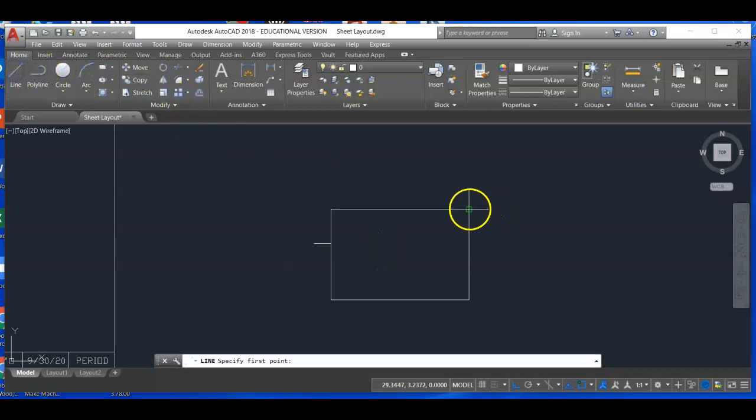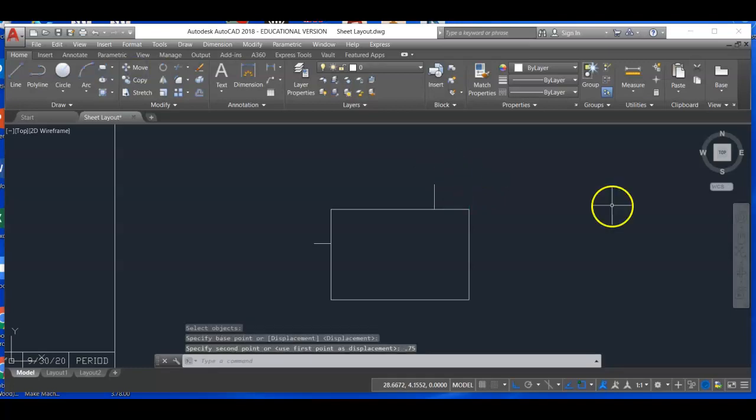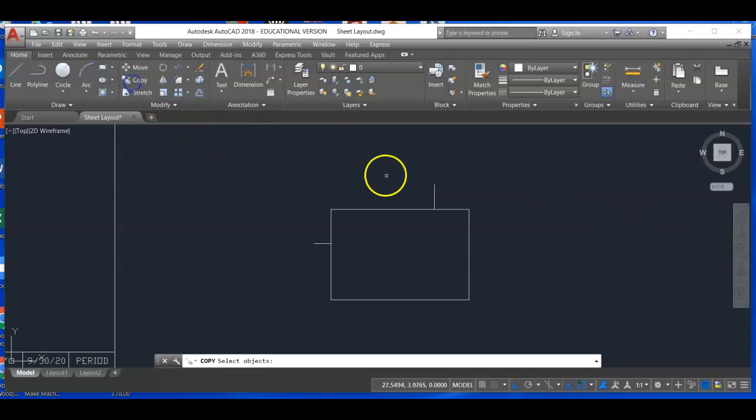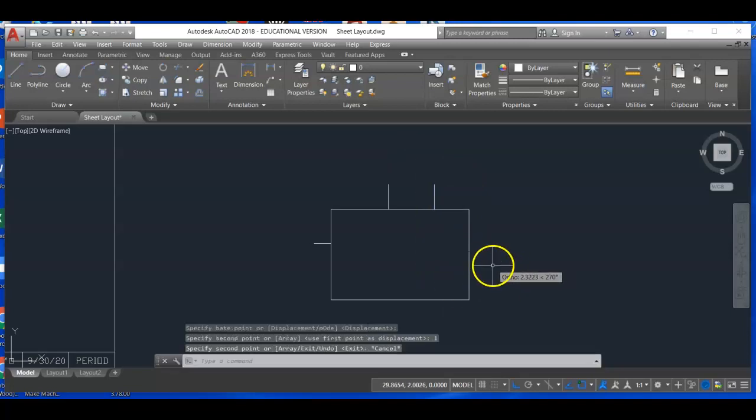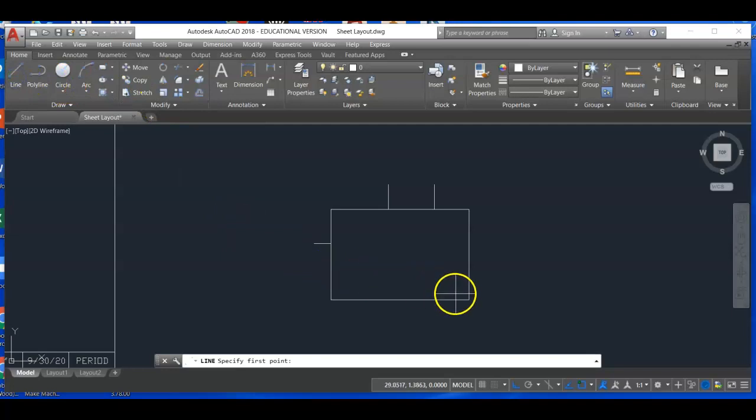Okay. Draw another line at the top corner. Notice I like to draw these rectangles, and this line here is any length. I like to draw these rectangles so I can reference from corner points. I'm going to move this over a distance of 0.75. Hit enter. Now I'm going to copy this line over 1 inch. Do the same down here. Hit escape. Draw my snapping point.